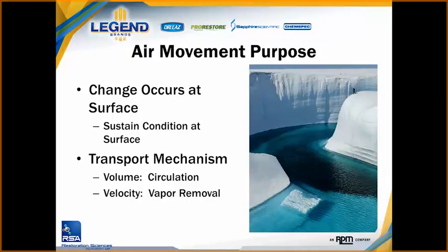It's actually something you can test just to prove out in your mind just how important that flow is to continue that change of state. Take an ice cube from the ice chest next time you're sitting around the freezer and throw that ice cube into a bowl, like a mixing bowl, with some normal tap water. Just watch how fast the ice melts. It'll be a relatively fast rate of melting at first, but then it's going to slow down dramatically. Then begin stirring the water, and as you stir the water, start observing how rapidly the rate of melting begins to increase. It's a pretty dramatic impact.